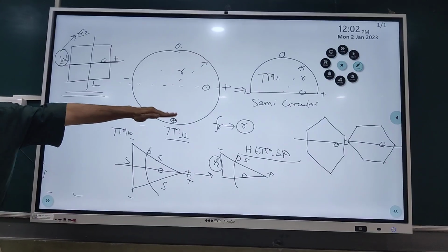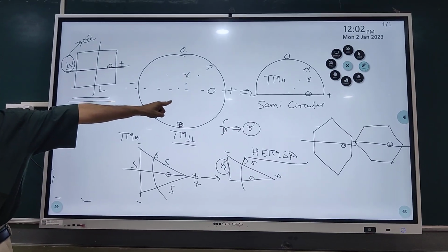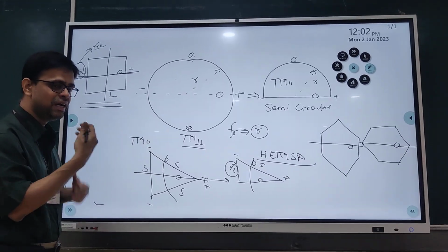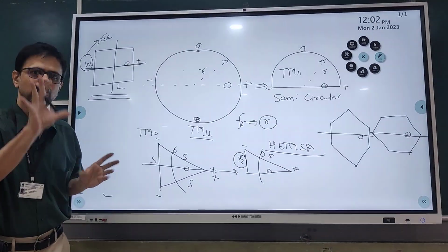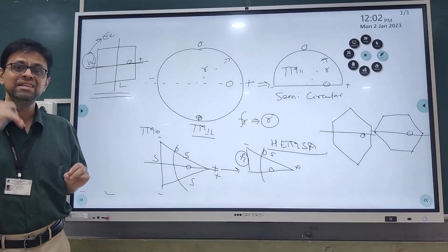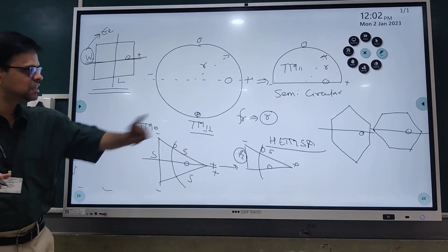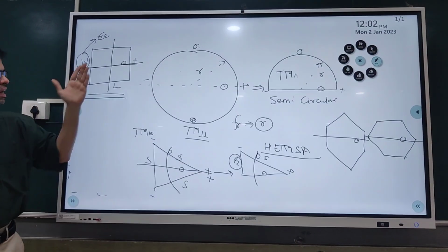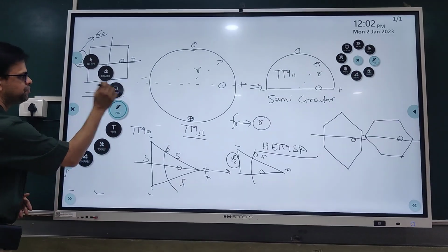Remember this, because the fields of the hexagonal microstrip antenna are similar in nature to the fields of your circular microstrip antenna. So depending upon the geometry, one can take a call by closely observing the geometry and then considering which parameter decides its resonance frequency. You can select a patch and you can realize a compact design using the symmetry of your configuration.